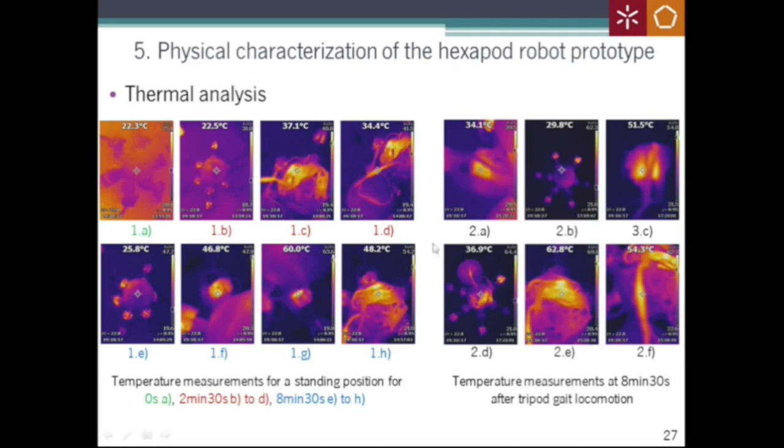Now, analyzing the robot in 3+3 gait, it turns out that it is not the servo motors of the R2 joints that heat up the most, but 4 servo motors of the R3 joints, as you can see in photo B. This may be due to the fact that these legs are repeatedly in more unfavorable postures, having to apply higher torques.